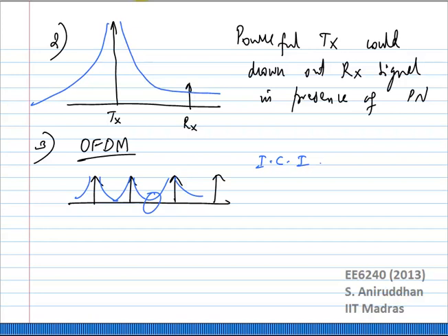Yes, you could have a linearity problem, but let us take the example of a GSM signal. The signal bandwidth is only 200 kilohertz. You are talking about spectral mask at maybe 20 megahertz away, which is actually quite far away compared to your signal bandwidth to actually cause any major problems due to linearity. Bigger problems will actually be due to phase noise rather than linearity.